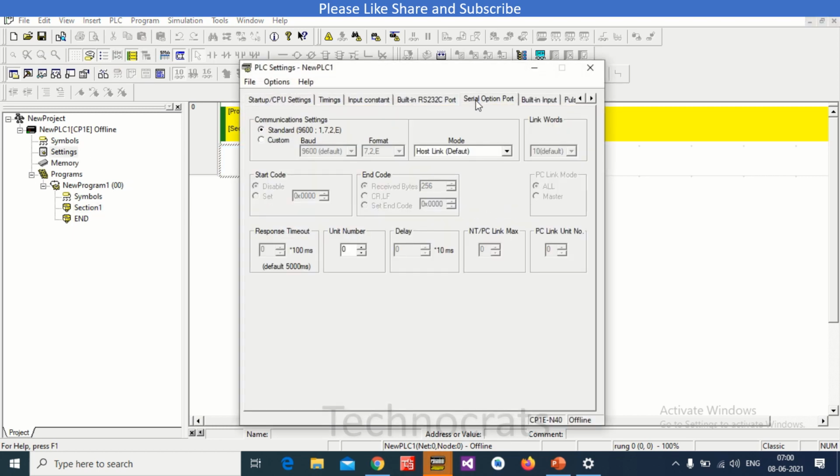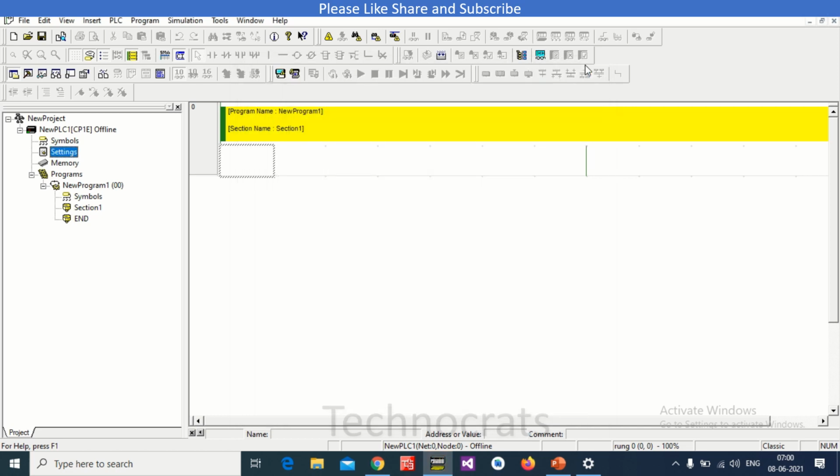option port. You will select mode as Modbus RTU simple master, and I am using standard baud rate, that is 9600, 7, 2 and even. You can use custom also if you require. So I will use standard here. That's all in the setting part. Now let's move to the program section.